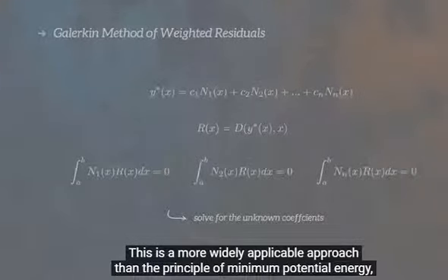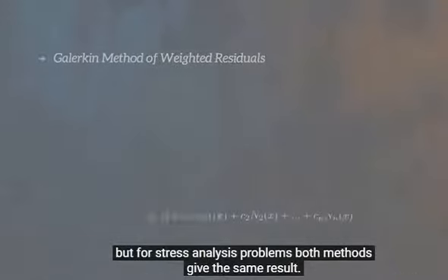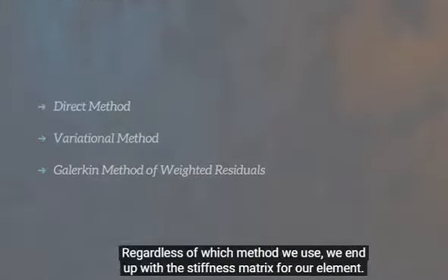This is a more widely applicable approach than the principle of minimum potential energy, but for stress analysis problems, both methods give the same result. Regardless of which method we use, we end up with a stiffness matrix for our element.